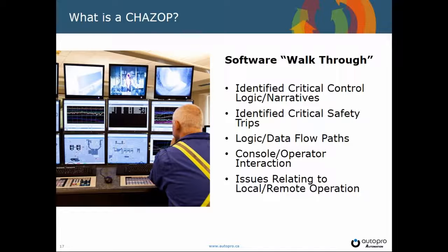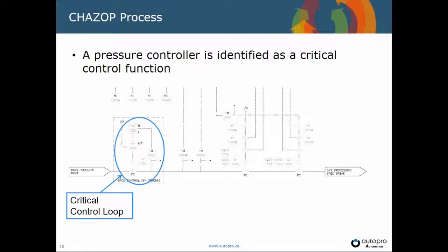And in that case, we put ramp buttons in, and we also put set point limits in, so that you couldn't step change more than, you know, 100 RPM at a time to minimize the risk of that.